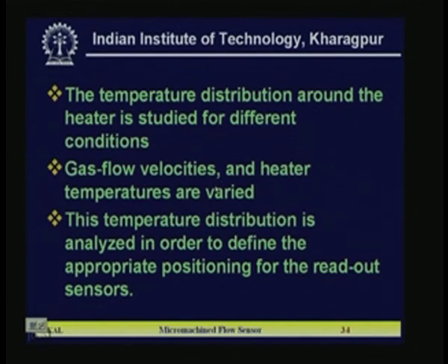Gas flow velocities and the heater temperatures are varied, and this temperature distribution is analyzed in order to define the appropriate positioning of the readout sensor. So, these are required for designing, meaning the proper positioning of the sensor and the heater on the silicon surface, so that you can go for making the mask.